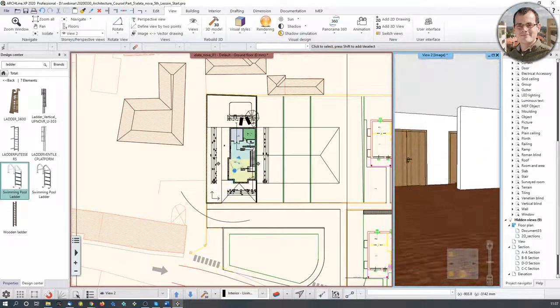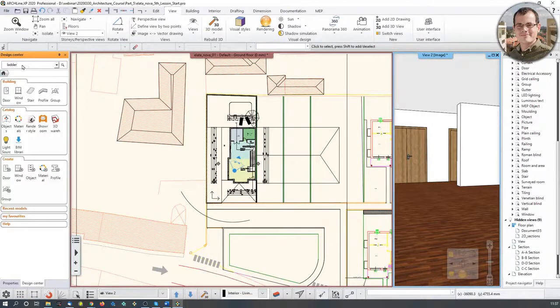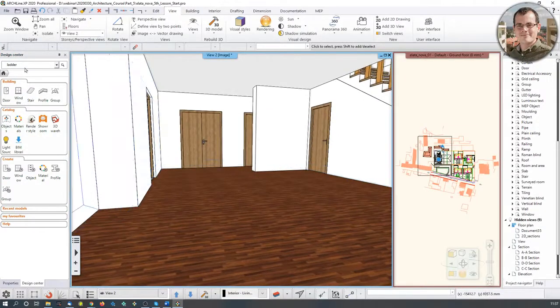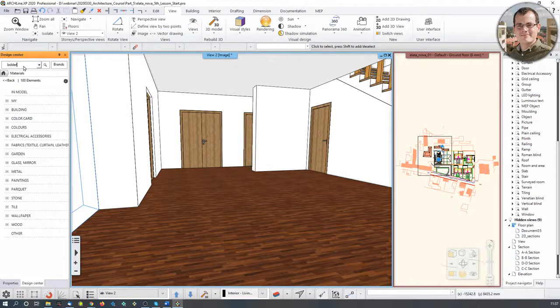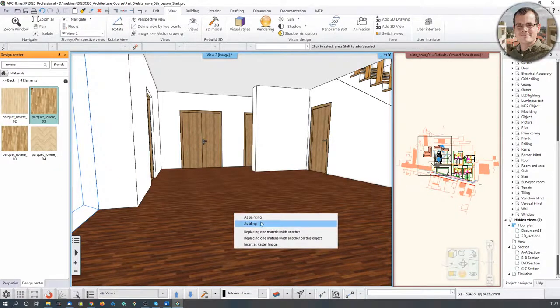Now, let's move into my drawing and talk about the content that we call textures and materials. I already showed you parts of this, so this would be partly a repetition. Let's say I want to change the texture of this property. So I'm just going to go to the material library, and I'm going to look for another texture, which would be this. Dragging and dropping, and now I have two choices. One choice is that I'm going to replace all the instances of this material with another one. The other one is that I'm only going to change it on this object.